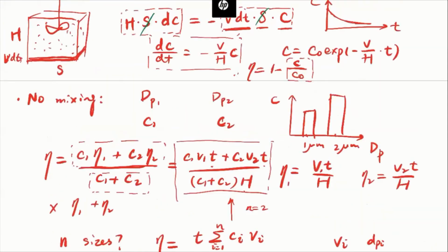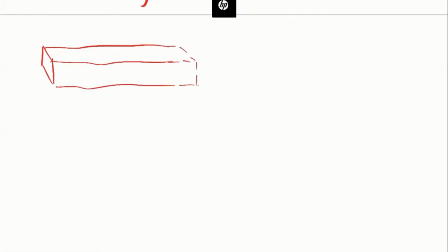So that's why we're not going to have these cube-shaped chambers. Instead, we can just use the duct to remove the particles in the flue gas, right? Because we always need to transport the flue gas into another location. For example, for the coal-fired power plant, once the particles are emitted, they have to go through all different particle removal devices and finally be sent to the stack, right? So while the particles are being transported to other locations, inside the duct, they can get removed, right?